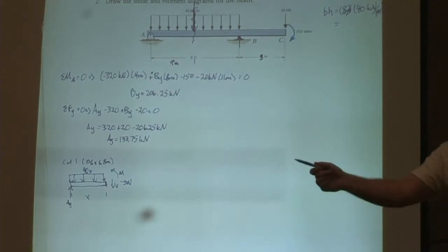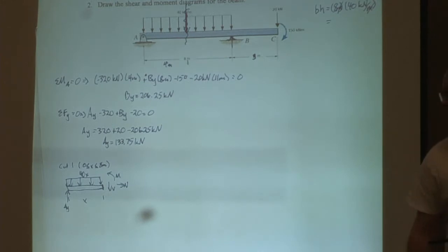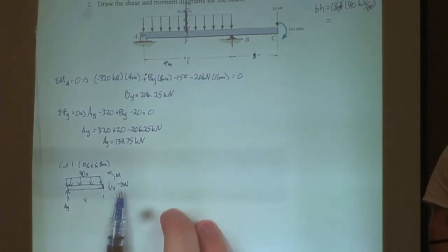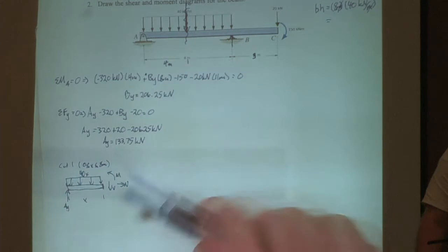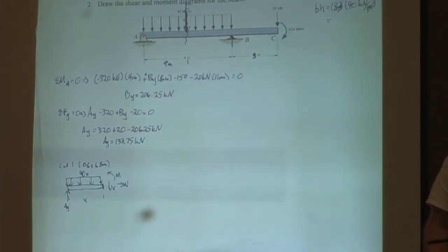And then to answer your question from earlier, the shear is an internal force, because if we make a cut left and right, the shears always have to be opposite of each other, right? Because we're in equilibrium. So it's always going to be the internal force that reacts on the body. All right, so looking over here, what's our normal force going to be? Zero, because we don't have anything in the x. All right. Now we have to solve for shear, and we have to solve for a moment, right? All right, so let's just start going through that.